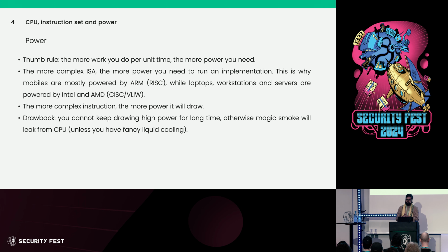How many of you have heard about SpeedStep and Turbo Boost? Just raise your hands. SpeedStep. Very few. Turbo Boost? Okay, how many of you have seen shameless promotions from CPU vendors? My CPU runs at 2.4 gigahertz and up to 3.2 gigahertz. So if you go below 2.4 gigahertz, that is underclocking, that is done by SpeedStep. And if you go above 2.4 gigahertz, that is overclocking, that is done by Turbo Boost.